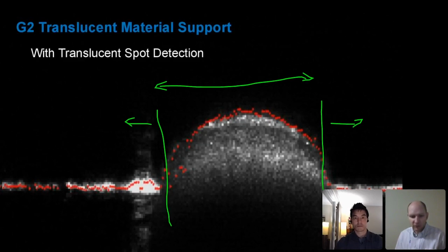I would say in general, if you are working well with just a single surface edge tool or two surface edge tools, that would probably be faster than using a surface pattern matching tool that's looking at the entire field of view, just because it would be operating on a lot more data. So I expect that would actually be slower. But in some cases, you could definitely be faster using the surface pattern matching tool, and more robust and more accurate, like I was saying earlier.